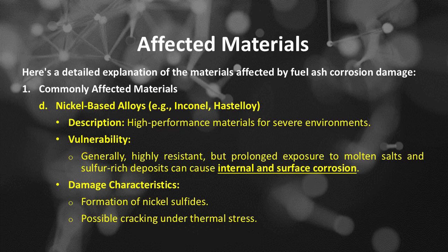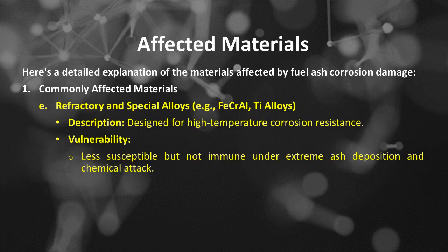Number D: nickel-based alloys, such as Inconel, Hastelloy. Description: high-performance materials for severe environments. Nickel-based alloys vulnerability: generally highly resistant, but prolonged exposure to molten salts and sulfur-rich deposits can cause internal and surface corrosion. Nickel-based alloys damage characteristics: formation of nickel sulfides, possible cracking under thermal stress. Number E: refractory and special alloys, such as FeCrAl, T alloys. Description: designed for high-temperature corrosion resistance. Vulnerability: less susceptible but not immune under extreme ash deposition and chemical attack.